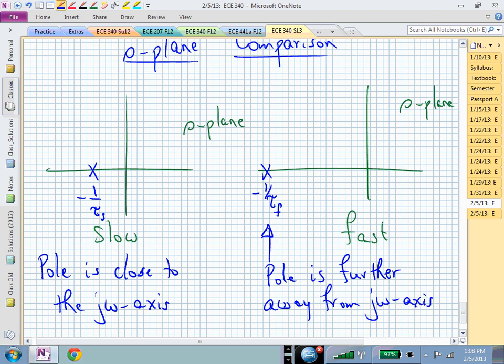And that's another frequency domain picture of what's going on. Meaning I could have given you this, and then you could sketch the Bode plot. And you could say, oh, I'm flat for a while, and then I break at this small frequency. Or I'm flat for quite a while, and then I break at this frequency, and then I start going down. And those two Bode plots could be consistent with this S-plane plot or picture.